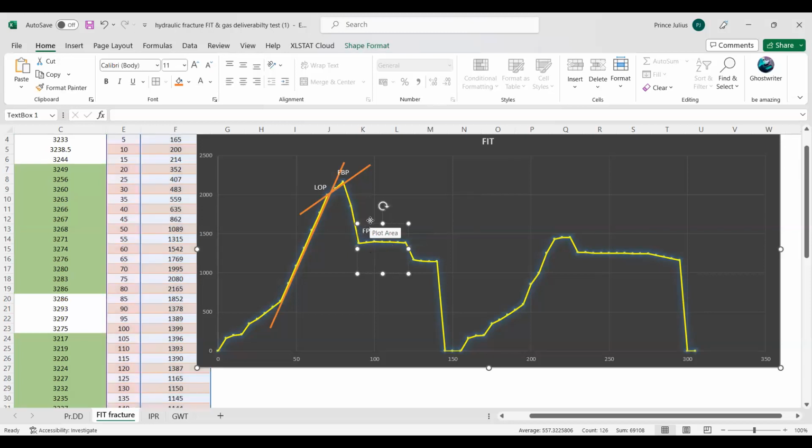Then after that, it has reached a position, and you stop injecting hydraulic fracturing fluids into the formation. That is when you stop injecting; that phase we name the shut-in period. So the initial shut-in started over here. So ISIP, initial shut-in pressure. From here, you can see the maintenance of the fracture is very less.